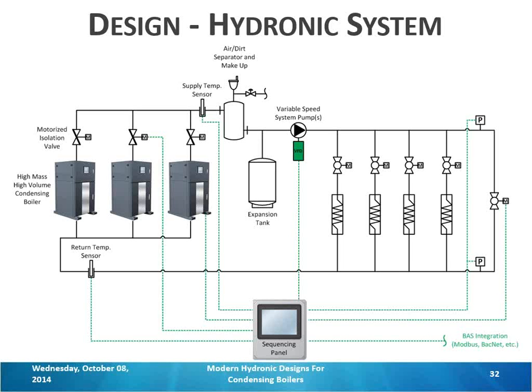The 20-degree delta T is used most often in traditional systems. And the reason why is they needed that 180 to 190 degree water. And by choosing a 20-degree delta T, you don't really risk condensing in that boiler. A lot of newer systems are starting to move to bigger and bigger delta Ts, but they're often limited by the coil size that's available. And at some point, the coils will just get too big and expensive, and it's not practical anymore.